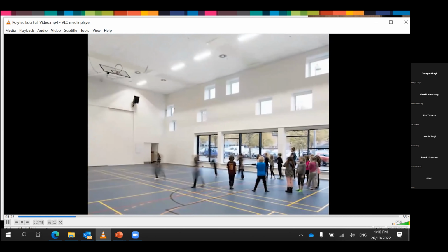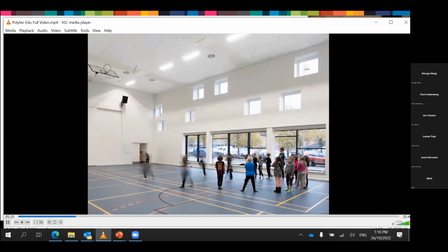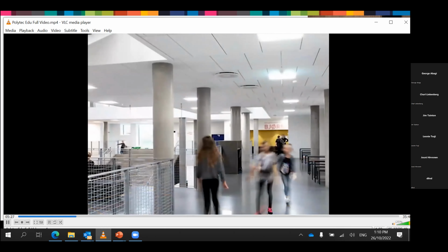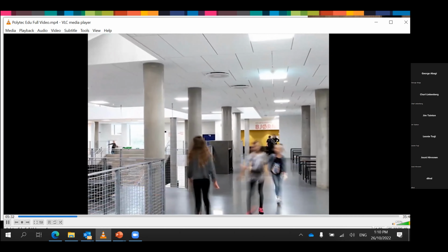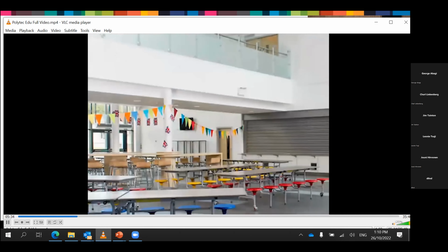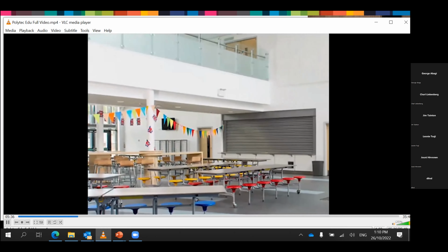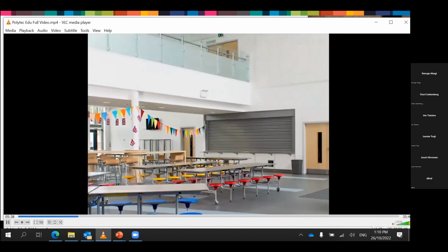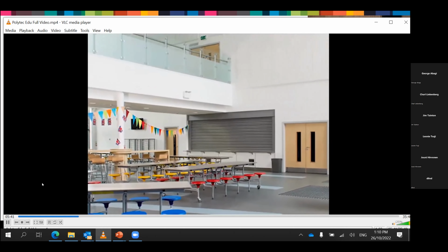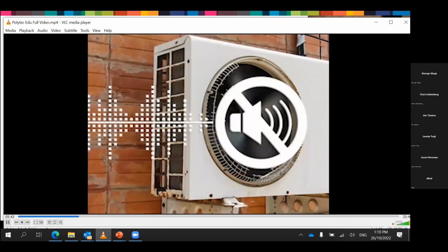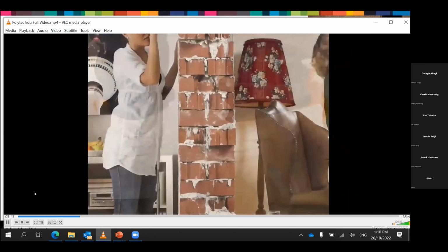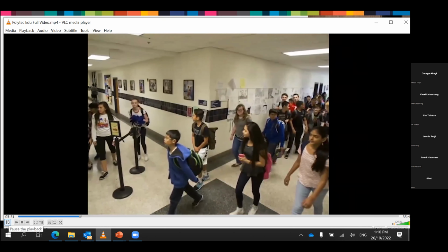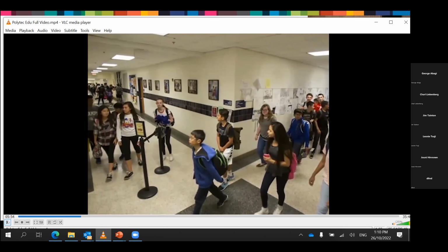The general trend towards creating flexible open-plan spaces, which can accommodate a variety of teaching methods simultaneously, also contributes to higher noise levels. Classrooms that are reverberant, with a lot of echo, or too noisy make it difficult for teachers to speak and children to hear and understand. Background noise from services, shuffling of chairs, foot traffic, adjacent rooms and corridors can also create disturbances which interfere with concentration levels and performance.